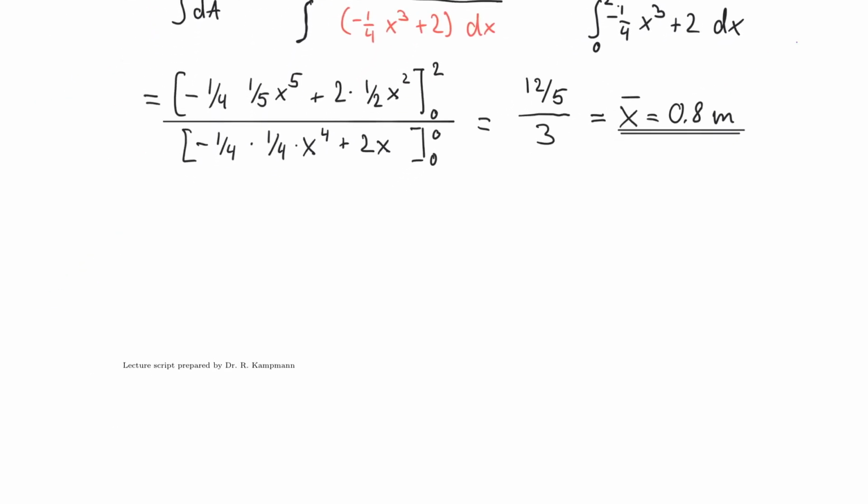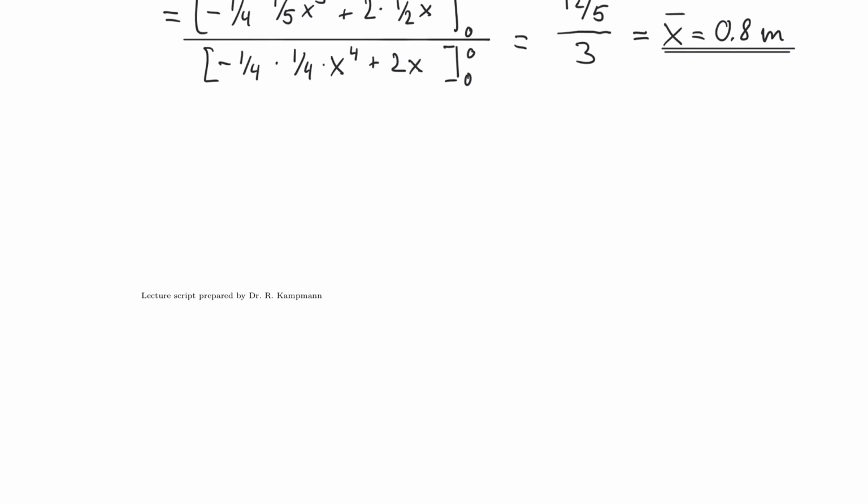So I'm going to do that down here. So F plate is equal to the thickness in meters, by the way, times the area in meters squared, which is a volume then, multiplied by the density, which usually is called rho. And that is usually in kilograms per cubic meter, but I'm going to violate that a little bit and go in kilonewton per cubic meter, because that's what we're ultimately after, as a force, right?